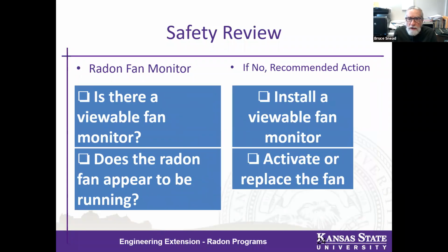Is there a viewable radon fan monitor? And does the radon fan appear to be running? The monitor or system indicator should be available for the homeowner or occupant to view on a regular basis, certainly at least weekly or more often. And is the fan running? The monitor would give you that indication. If it's not, then the recommendation would be to activate or replace the fan.